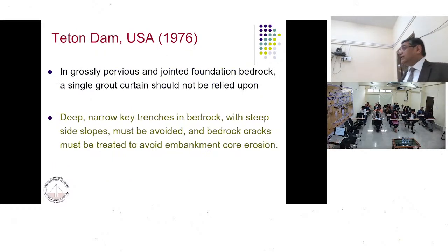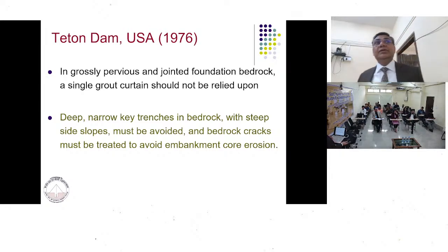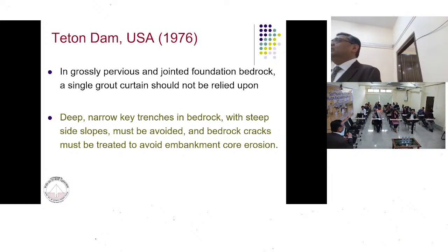Secondly, we also learned that in grossly pervious and jointed foundation bedrock, a single grout curtain should not be relied upon. So they had provided a single grout curtain, and actually what is grouting? You know what is grouting? How do we do it? You drill a hole and then you inject cement grout into it.